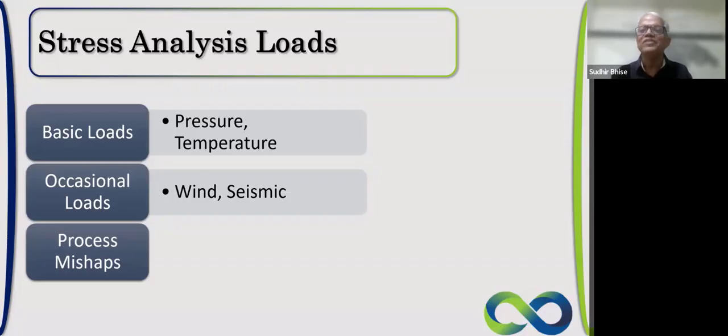Yes, PSV reaction. That means a blowout of a PSV. Whenever a PSV blows, you are going to experience some reaction in that zone, and we need to take care of this. So our focus for today is going to be these three types of loads: basic loads, occasional loads, and the process mishap loads.